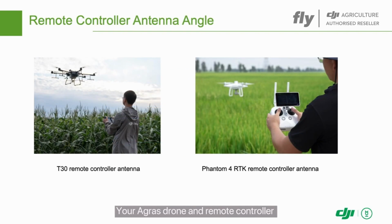Your Agras drone and remote controller have already been linked prior to delivery. You won't need to link them unless you change the remote controller. To complete linking, tap Linking on the remote control app, and then press and hold the power button on the drone for 5 seconds.